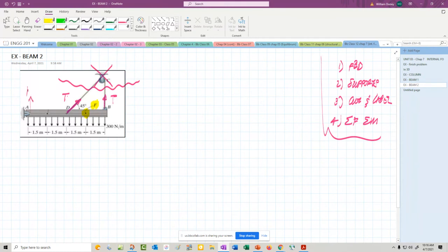And then from there, I can put an AY over here, and I can put an AX. Now, since there is a component in the X direction of the cable at D, we now will have some force set up in A. We can expect some force set up in A. All right, so what do we do? Draw a free body. Let's find supports.